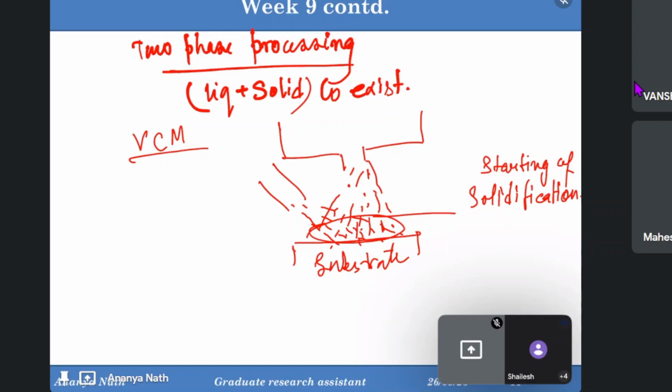Because of supercooling. Yes, because of the supercooling, the dendrites are generally formed due to the temperature gradient between the interface of the solidified protrusion and the melted metal. And these dendrites grow with time in the melted region, and due to the effect of shearing or external forces, or due to any reason, the dendrites may get broken, because those are just expanding their arms in the melted aluminum.